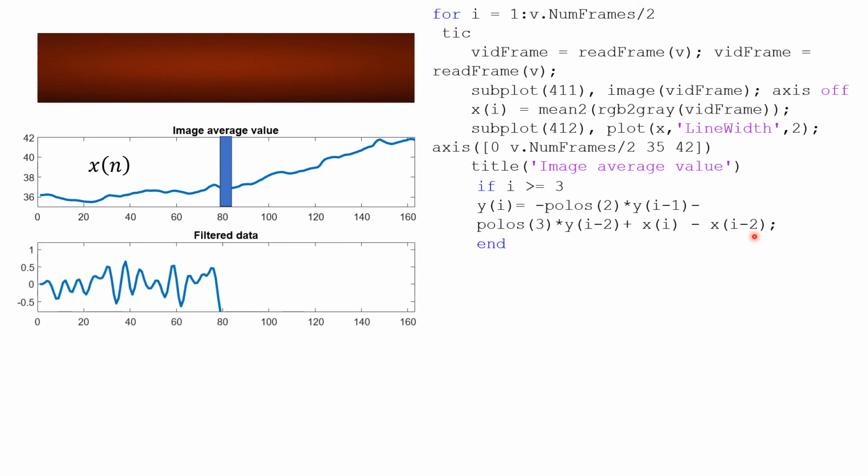So I will be obtaining filtered data like that. Notice how I can see those oscillations corresponding to the heart rate, and now I need to decide how to calculate the beats per second. In order to do that, I need to see the frequency of these oscillations, and one way to do it is to use the Fourier transform. So now I have to decide on a length for the Fourier transform, maybe around 30 or something like that, which is highlighted in the yellow part here.